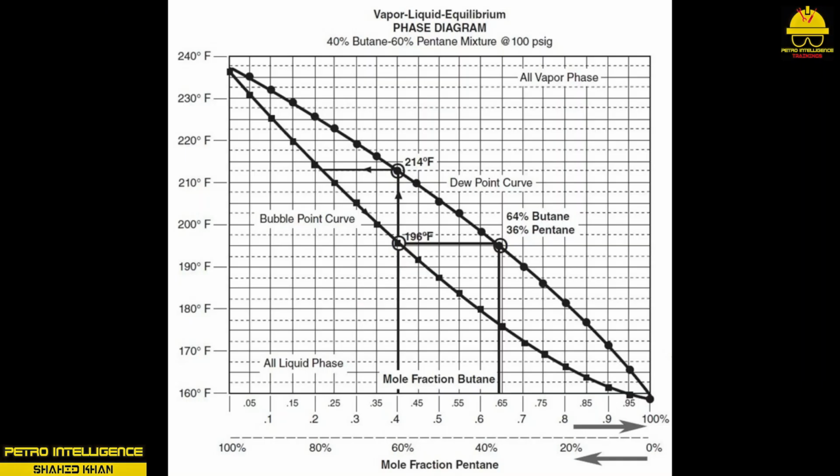Each of these areas is important for a technician to understand in order to work in and operate a distillation system. This picture is often referred to as a vapor-liquid equilibrium (VLE) diagram or phase diagram. It provides a simple way for a technician to visualize the complex phase behaviors associated with distillation, boiling, and condensing of a two or more component mixture.